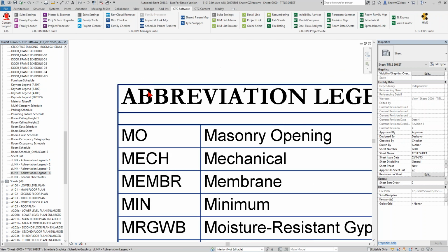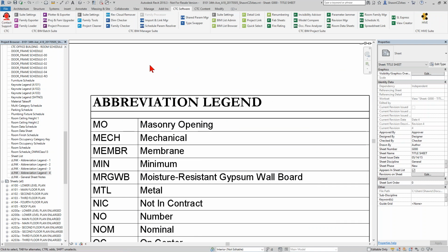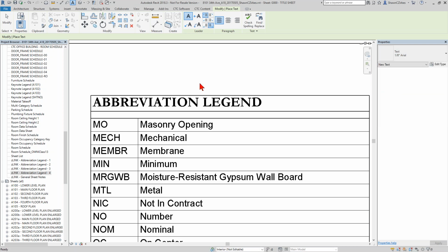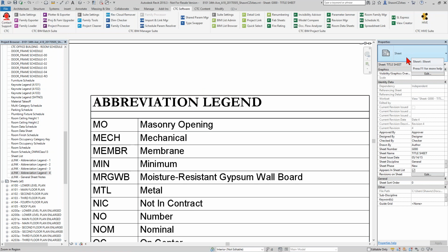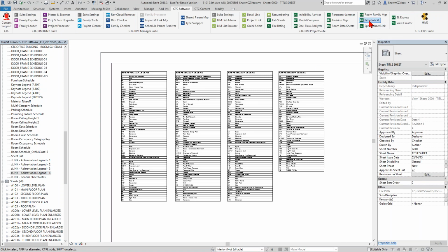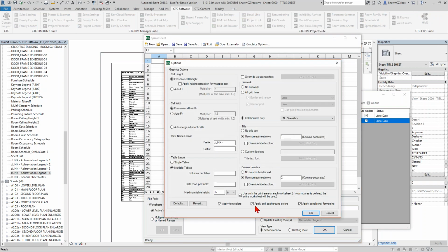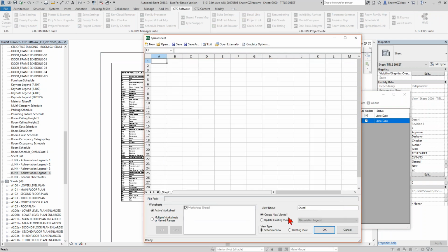And so in this case, I've got this Book Antica style font, and if I was to call up the regular Revit text command again, there's no additional font types over here because it doesn't need them. The schedules, the way that we use this, it doesn't create any new text types. That, by the way, is the primary reason when I'm using Schedule Excel and creating a link to an outside thing that I always prefer to use the schedule view instead of a drafting view.